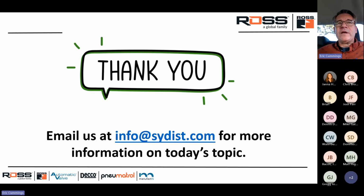And so in summary, when you look at e-stop, a few things are clear. It doesn't just apply to electrical. It does include the fluid power. And when you look at what type of e-stop circuitry you have in there, from an electrical and a fluid power standpoint, it's going to be based on that risk assessment.